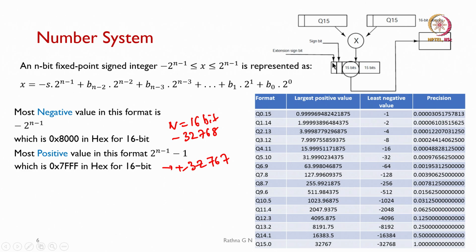So, we call this an extension of the sign bit, and we will be discarding it, and then we will be taking the 15 bits, that is the MSB bits from our output, and storing them in the memory. This we call truncation. If I know that most of the values are in these higher 16 bits, then I can do the truncation. But sometimes rounding may be required, because most of them may be 1 in the LSB bits.